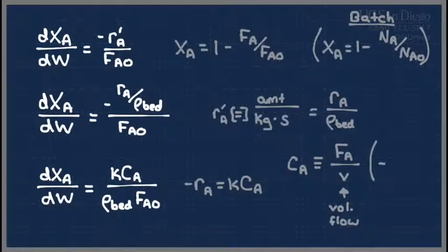And if you compare that to the way that we had done this for a batch reactor, we had said that was NA over volume with a capital V. So that's a subtle difference. The reason that that's a subtle difference is because if we're dealing with a gas, it's never the case where we don't have to use that giant expression for CA0. We always have to use that expression for a gas in a plug flow reactor because it can move back and forth along the axis of the reactor. The volume is never considered constant in that particular sense.